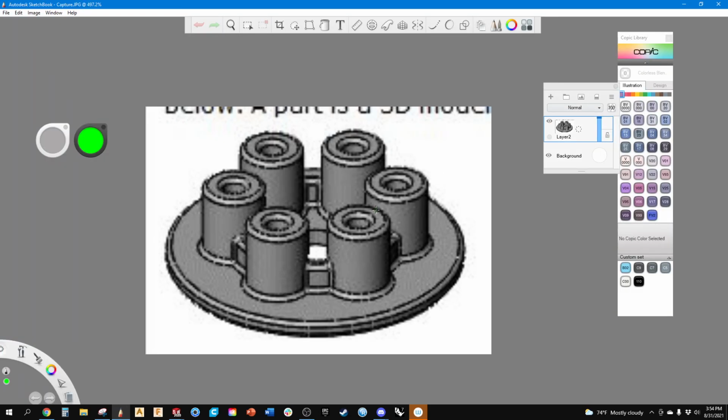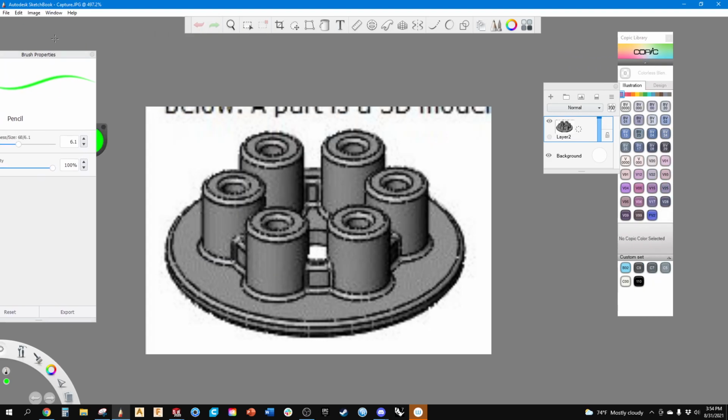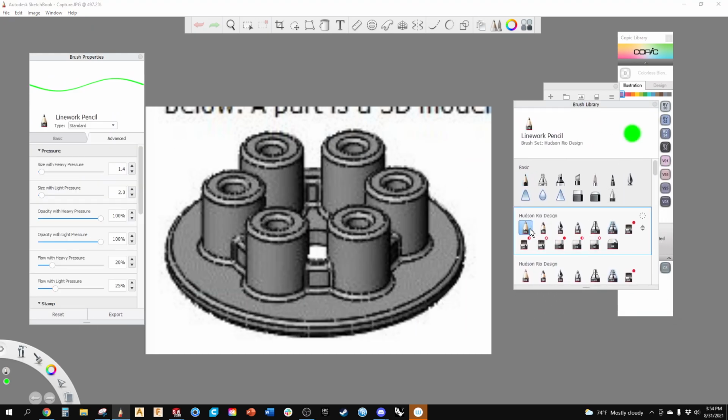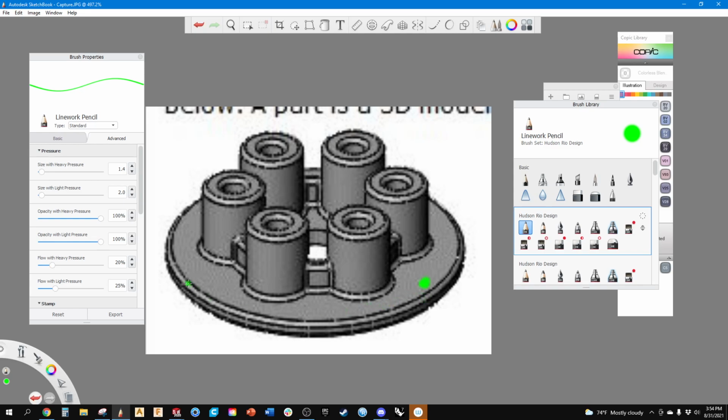When I look at this, if someone gives me this part, before I start modeling, I try to figure out what I am going to do. I'll quickly say, okay, what are the characteristics of this item that I'm going to model here? The first thing I'm going to model is basically a circle that's extruded as a cylinder.